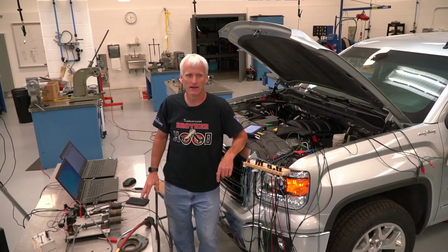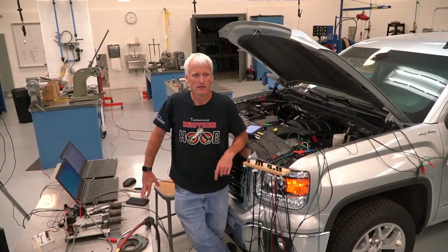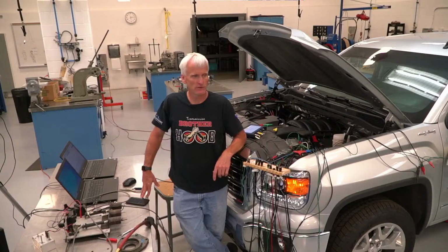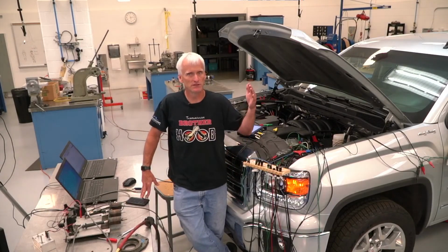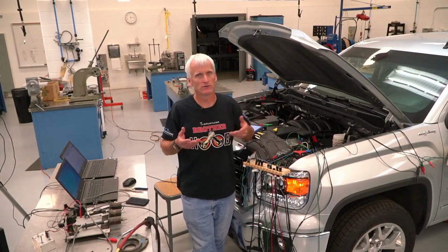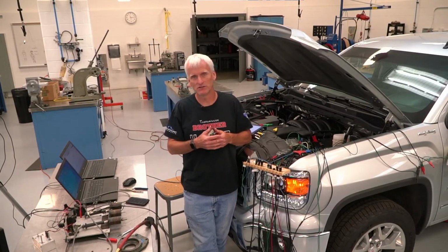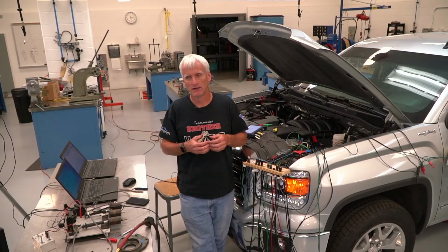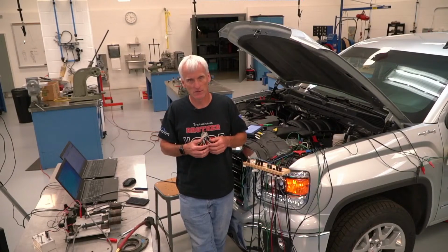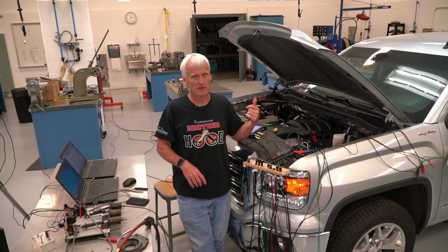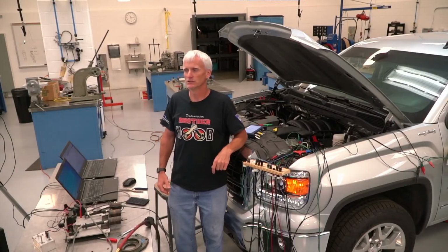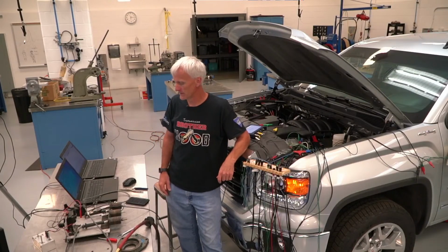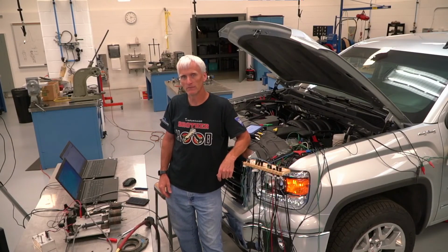But then I also did it on a turbocharged WRX, and it's a little different doing a VE test on something that's turbocharged, because you have to take into consideration the fact that it's boosted. You're not just putting atmospheric pressure in there, you're squeezing more air in there. And it was kind of interesting to see that it pushed 255 grams of airflow per second through that engine, which is 50 grams of airflow per second more than the Tahoe, yet that's a 2 liter compared to a 5.7 liter. So it shows you that pretty much everything should have a turbo or a supercharger. That's basically a new thing now that I believe.